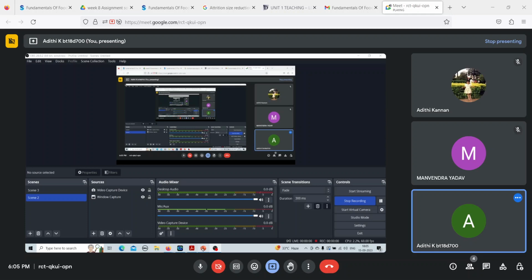So if you want to look at the crushing efficiency formula, here Wn equal to Es (AWB minus AWA) by eta C, where Es is the surface energy per unit area, AWB and AWA are the area of a unit mass of the product minus that of the feed, divided by eta C, which is the crushing efficiency, and Wn is the energy absorbed by the unit mass.